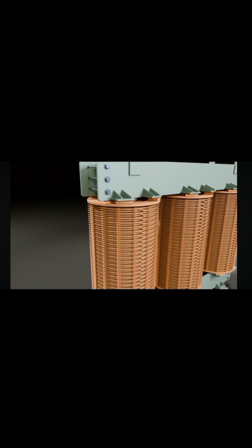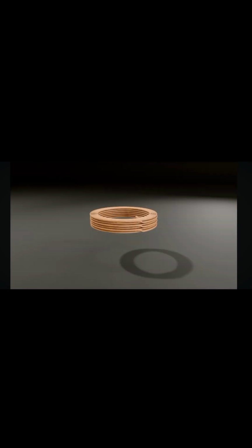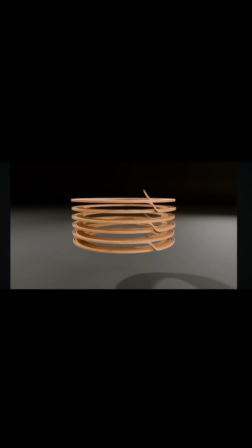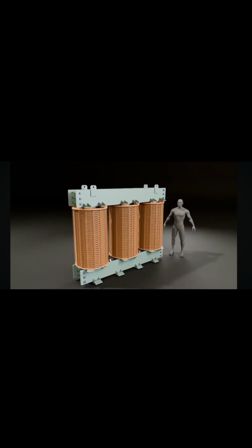High-voltage windings have a greater number of turns compared to low-voltage windings, although the conductor cross-sectional area is significantly smaller. HV windings are typically wound using continuous disc windings. In a continuous disc winding, conductors are wound in continuous spirals, alternating from inside to outside and outside to inside, forming disc-like structures. These discs are connected through inner and outer crossovers. The continuous disc design ensures more uniform voltage distribution across the winding, reducing the risk of insulation failure.